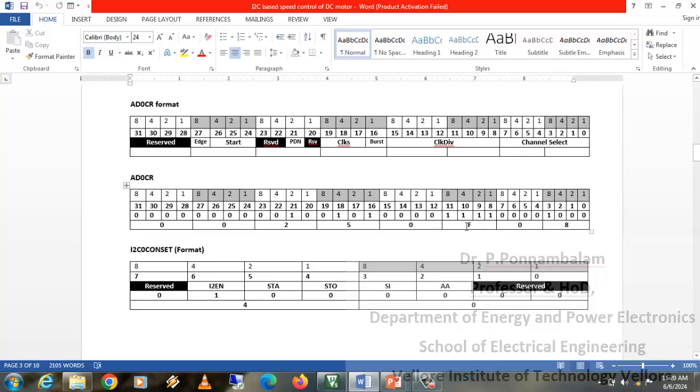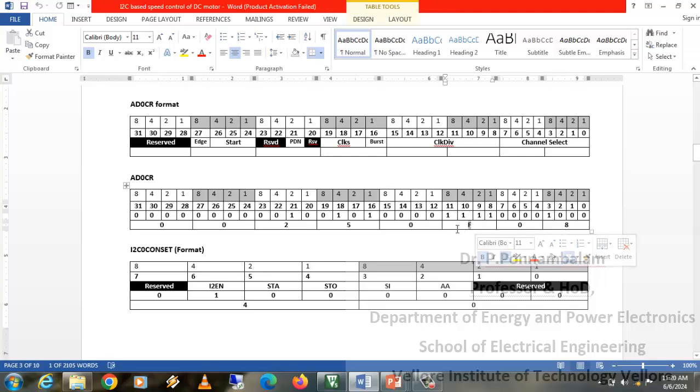As far as your hardware is concerned, when I have this f, it gives a smooth transition, and the transmitting and receiving on the other side of your microcontroller happens to be smoother. Then the third bit I am making high to select the channel. So the third channel of AD0 is selected by making this third bit high.